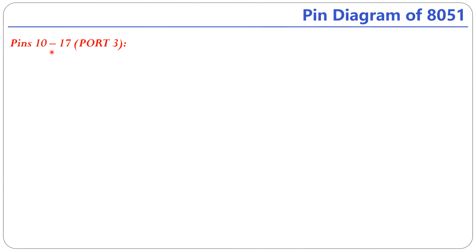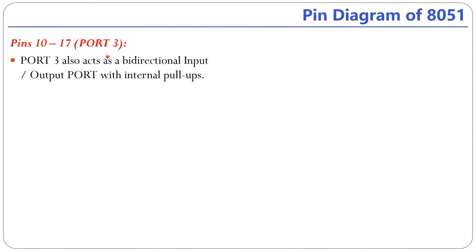Pin numbers 10 to 17 represent port 3. Port 3 also acts as a bidirectional input-output port with internal pull-up resistors. Additionally, all port 3 pins have special functions.